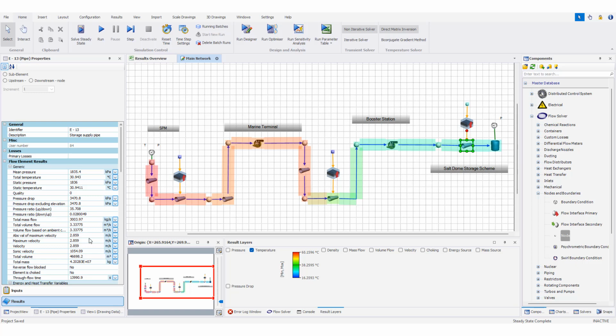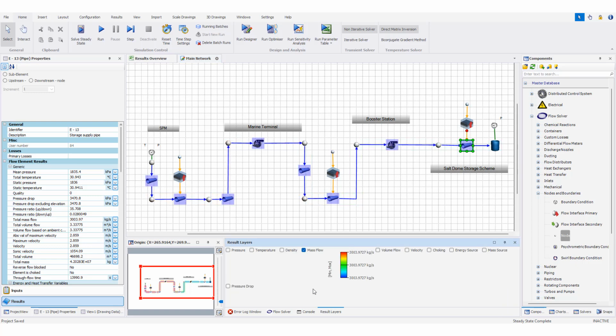These are all for the temperature variation in the pipeline. As you can see, in the reservoir, now the temperature drops to 29.9. It used to be 61, 62 degrees. So now it reflects better the reality, the physics of the problem. We can also check mass flow rate. For this one, again you can see that the total mass flow rate, as we already saw, is almost 30,000 everywhere the same. But if we check velocity, it depends on the pipe diameter.